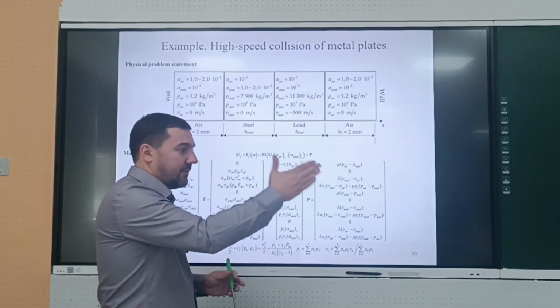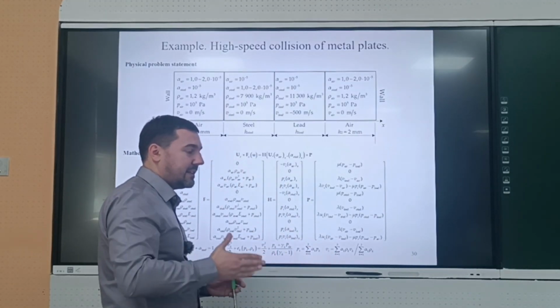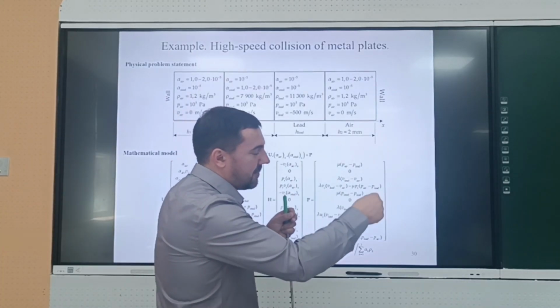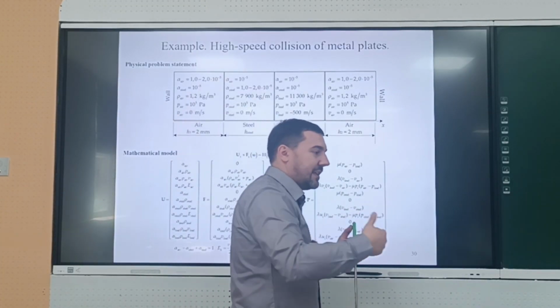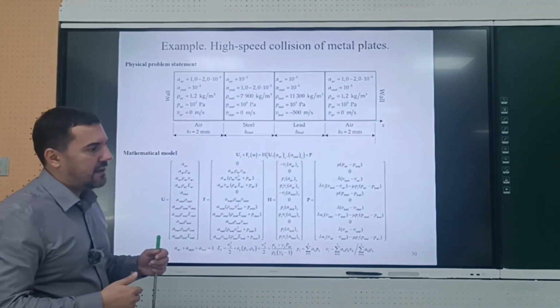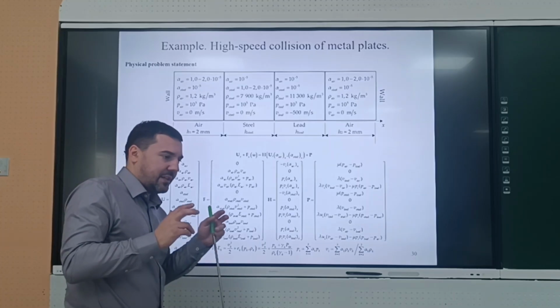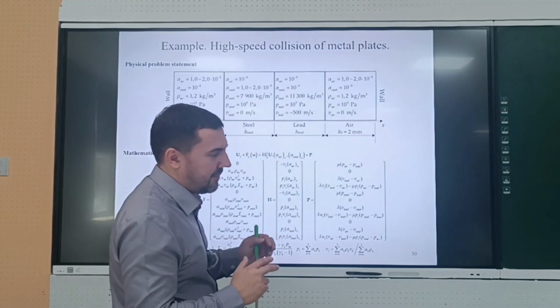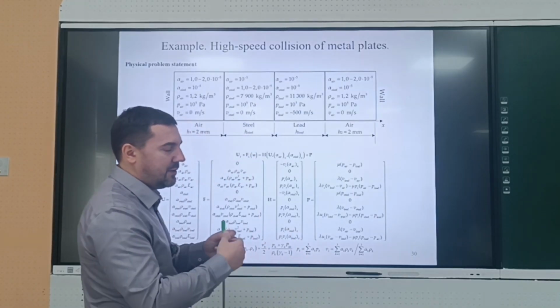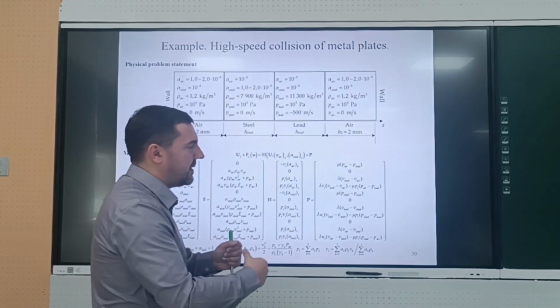If you then cut this specimen, you will see that at the interface boundaries there is a sort of hydrodynamic instability. Because at the moment of impact with a huge velocity of several hundred meters per second, the metals behave like pseudo fluids, and you obtain a sort of instability at the interface boundary. It produces this process of welding.